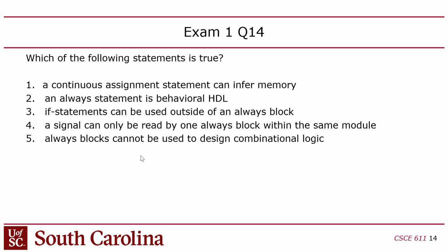A continuous assignment statement can infer memory. Not true. A continuous assignment statement is one that begins with assign, right? As far as I know, there's no way to get memory with an assign statement. An always statement is behavioral HDL. Yes, behavioral as opposed to structural, right? So yes, that's true. That's the answer, right?